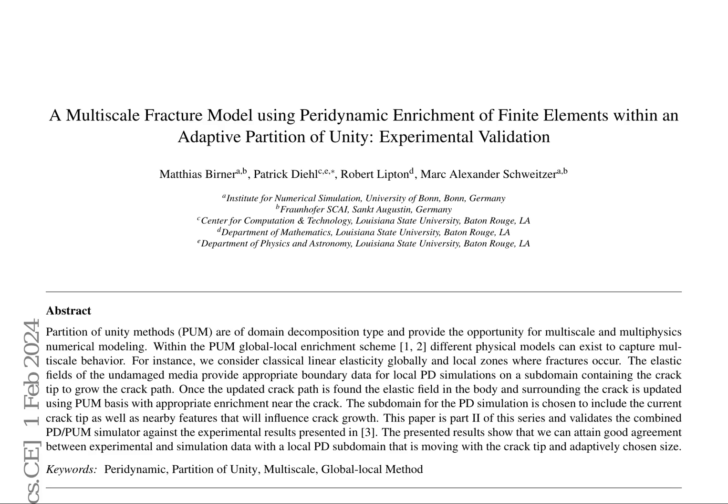This research paper presents a novel multiscale fracture model that integrates peridynamic enrichment with finite elements within an adaptive partition of unity framework. This approach enables the capture of multiscale behavior by leveraging different physical models, such as classical linear elasticity globally and local zones where fractures occur.